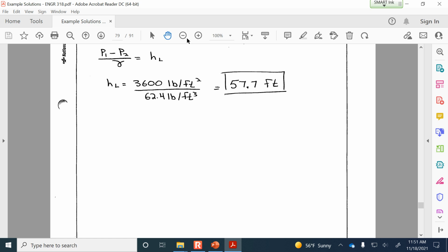Okay, so our formula for head loss is H sub L is equal to 0.025 times length times velocity squared divided by 2g. And I can rearrange that algebraically, like if I'm solving for V, V will be 2 times g times head loss divided by 0.025 times the length, and then all of that is to the 1/2 power.